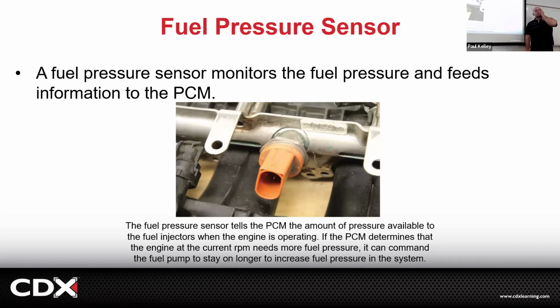Ford likes to use those. And any car that has gasoline direct injection will have it. But for example, I'm actually good with knocking my own brand here. The domestics are good about putting fuel pressure test ports on the fuel rail so you could easily connect a gauge.